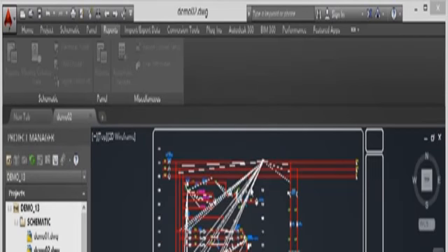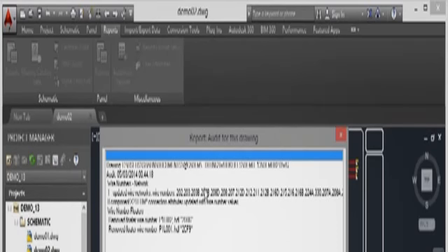So when I click on OK, it goes off into the drawing now, and it's found 173 line entities, 173 that are wires, and there's 0 wires on the no wire numbering wire layers shown in magenta. If I just move this down here for the moment, it's gone through and audited all of the wires. They're all marked in red, and all of these lines going out are AutoCAD Electrical checking all of those links between the wires themselves. So that's great. We're done. We have no errors, so I can OK that now. And there's the audit report.